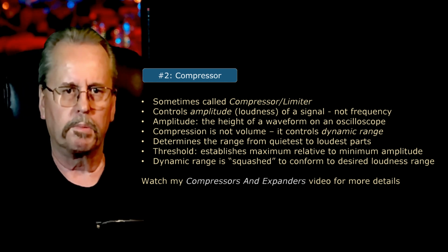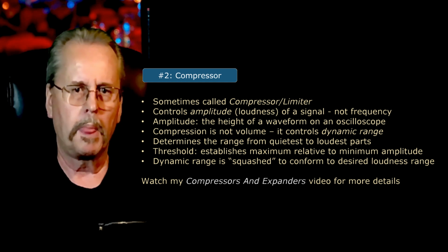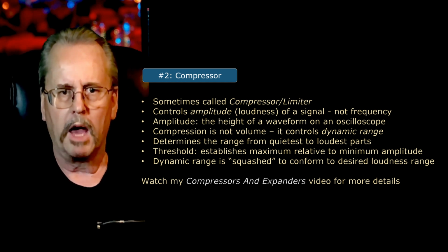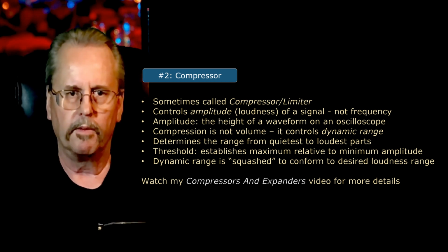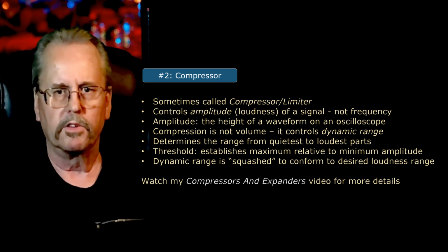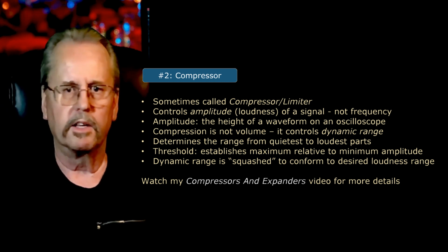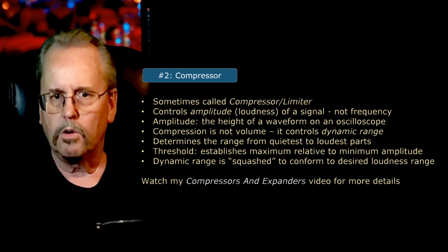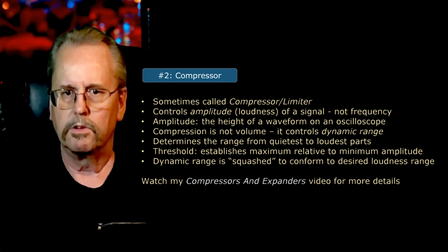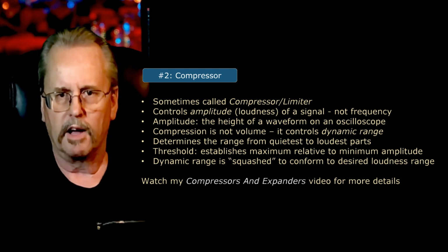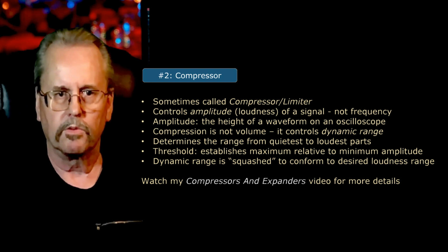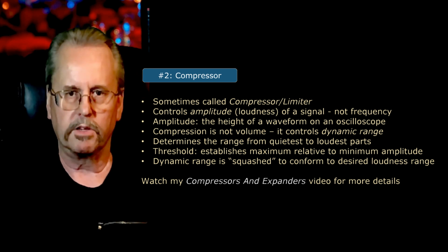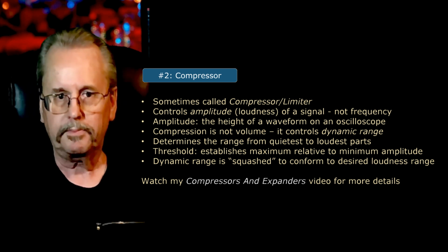Sound engineers use compressors to establish a threshold. A threshold is a maximum amplitude that the signal can reach before the compressor begins to affect the signal. Once this threshold is reached, the compressor will begin to kick in and start to squash the signal's amplitude to ensure that it never exceeds the desired maximum. Reducing the loudness range of a signal in this way is known as compression, hence the name.